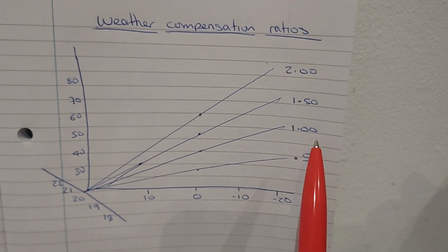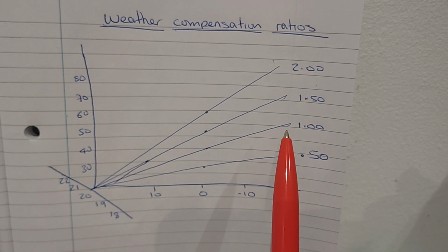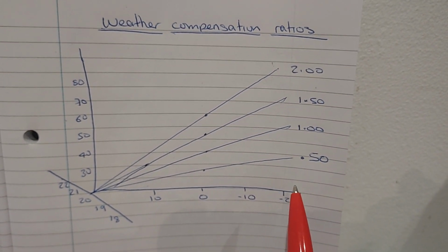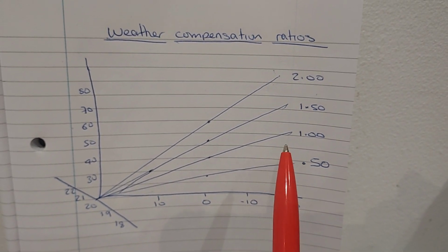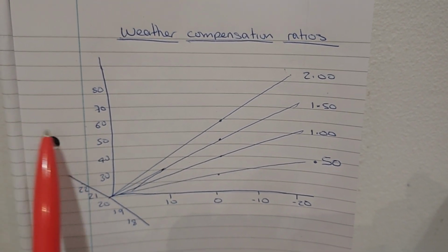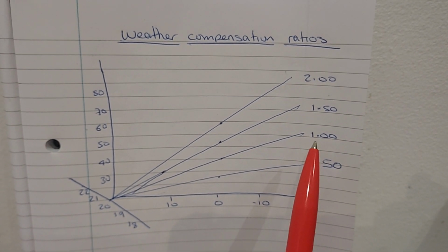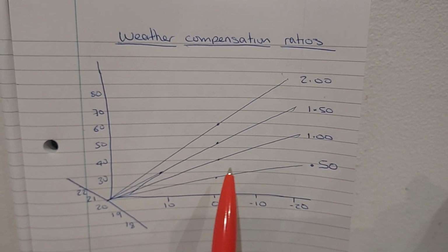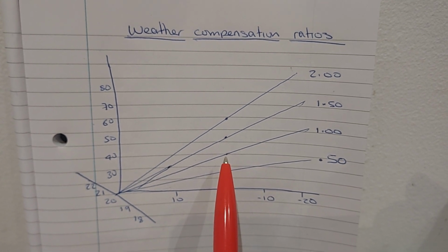Now, if you look along the 50 degree line, it's minus 20. If you had a curve of 1, which actually I do see a lot on underfloor heating, you'd be looking at a suitable temperature to heat to minus 20. Completely ridiculous and a complete waste of energy. So don't be doing it, boys. Design your systems for low temperature. So a top end of underfloor heating should be a ratio of 1, and we would expect at 0 to be running around 40 degrees.